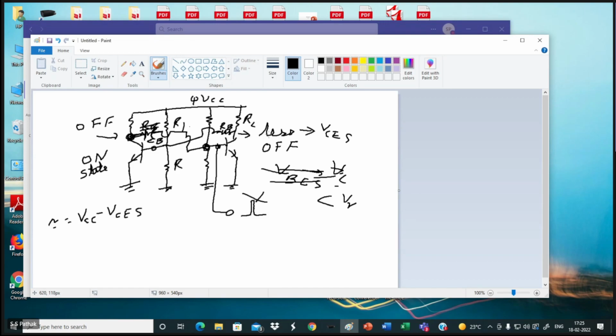Then this voltage becomes high. So what happened? When this pulse is applied, a high voltage appeared at the V naught. This is my output. Cutoff voltage remained high. After that, it starts decreasing. It comes down to this point, depending on the time constant, like this. So this CB, RC is discharging through these resistances. This was your R1 and R2, like that. It is discharging with this.